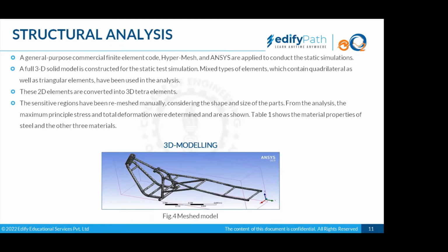Say you put on road conditions, or you put on which part stress would be applied, and if it is moving at such a speed, which part would be vulnerable, where most of the forces would be acting. A full 3D solid model is constructed for the static test simulation. Mixed types of elements, which contain quadrilateral as well as triangular elements, have been used in the analysis.